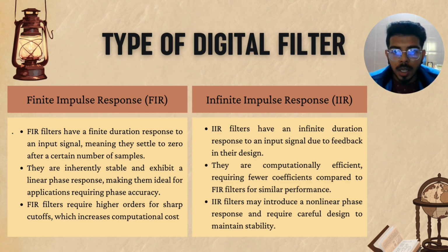And then IIR. IIR filters have an infinite duration response to an input signal due to feedback in their design. They are computationally efficient, requiring fewer coefficients compared to FIR filters for similar performance. And lastly, IIR filters may introduce non-linear phase response and require careful design to maintain stability.